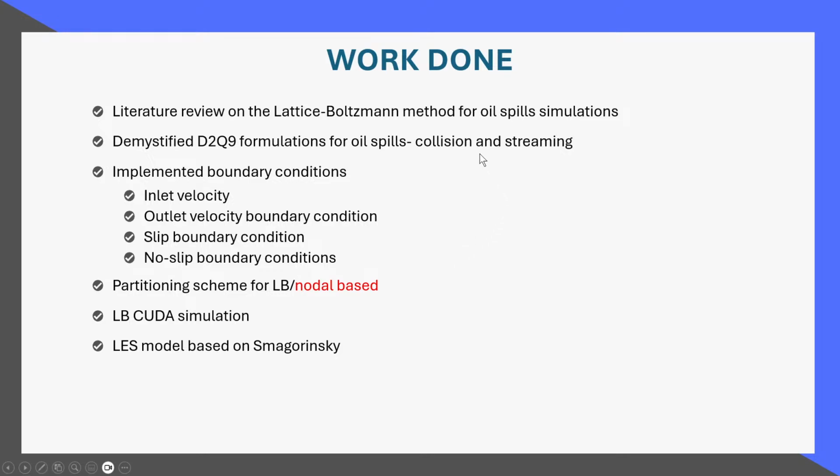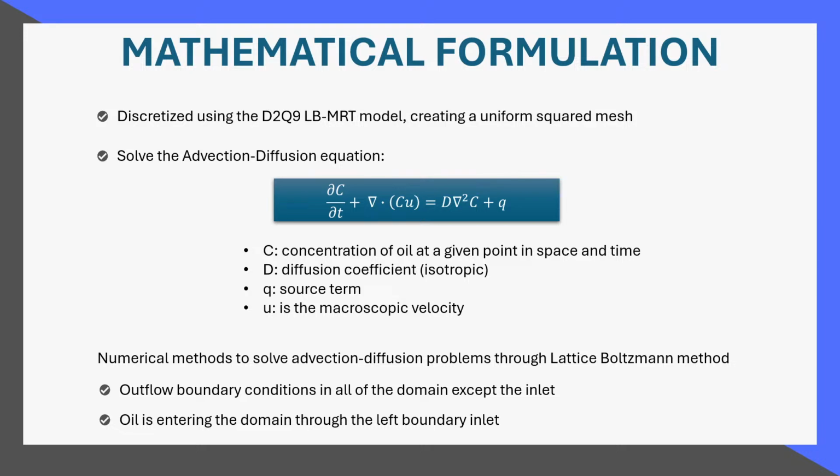Some of the work done: we conducted a literature review on the lattice Boltzmann method for oil spill simulations, demystified the D2Q9 formulation for oil spill collision and streaming, and we implemented boundary conditions for inlet, outlet, slip, and no slip. We devised a partition scheme for lattice Boltzmann nodal-based simulations. We conducted the lattice Boltzmann CUDA simulation and implemented the LES model based on Smagorinsky for oil spills. Here, as we can see, we discretize the D2Q9 lattice Boltzmann MRT model, creating a uniform square mesh, and solve the advection diffusion equation.